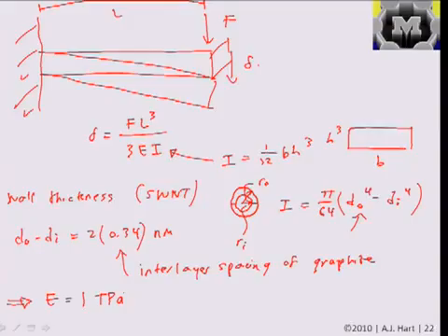By doing some more thorough calculations, we can derive that the modulus of a nanotube can relate to its number of walls because of the coupling between the walls and the effective spacing. If you end up with a nanotube that has a very large number of walls, you end up with a result that just drops out to the result for deforming a stack of graphite, because the hole in the center of the nanotube isn't so important. But if, for example, we have this nanotube which is hollow, and we bend it, then this bending model is considering that we have a hollow structure, and therefore we're effectively accounting for the material that's missing from the center.